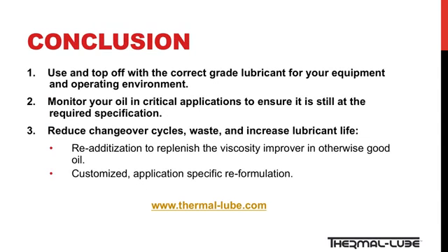One, make sure you're using and topping off with the correct grade lubricant for your equipment and operating environment. Operating a logging conveyor in the tropics versus northern climates requires different viscosity profiles. Two, monitor your oil in critical applications to ensure it is still at the required specifications. Most lubricant analysis labs can report the viscosity of your samples.